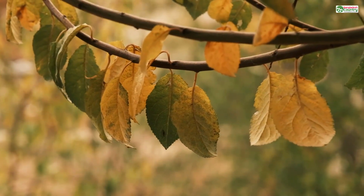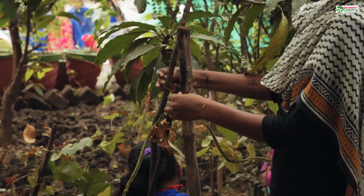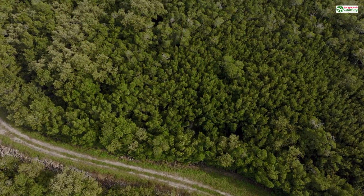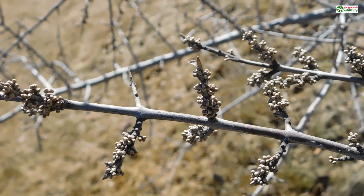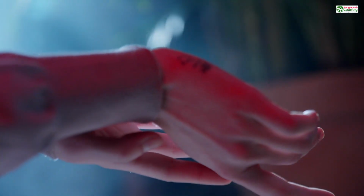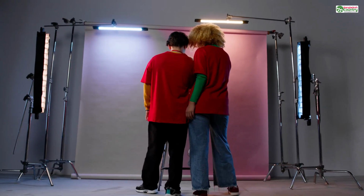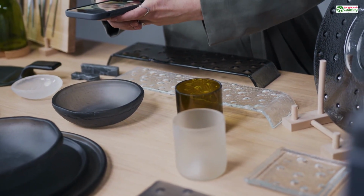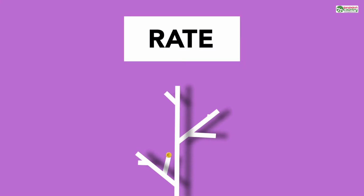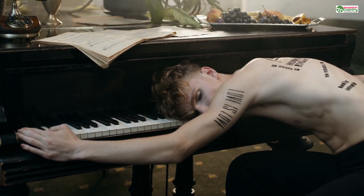Then there's the more elegant solution: tree supports. Instead of dense walls, tree supports look like, well, trees. They start with a few thick trunks at the base, and then branch out into smaller and smaller limbs, reaching up and touching only the most essential points of your overhangs. Think of it as the difference between building a solid brick column and using a carefully designed, organic-looking scaffold. The advantages are huge. Tree supports use significantly less material, which means a lower cost and faster print time. They are often much easier to remove, sometimes snapping off in one clean piece.